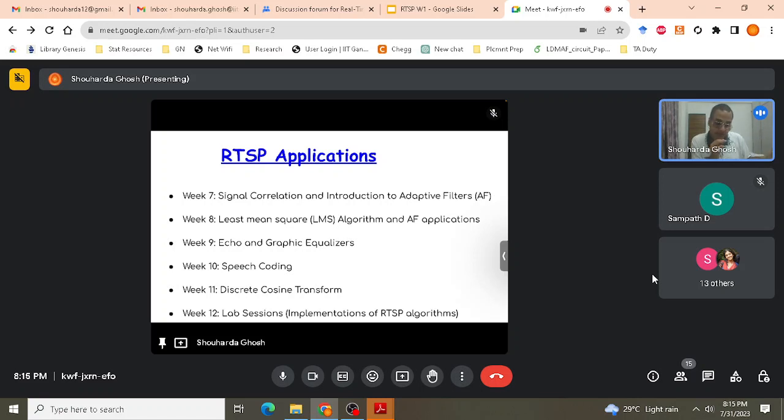Now what actually happens in the experience of the auditorium, how are you able to get that? In reality, the auditorium experience, the reflections, can be modeled by an impulse response. See, I am using a concept of signals and systems to explain what happens in your mobile phone. Your room, our communication, the auditorium's reverberations can all be modeled by an impulse response. And when I say they can be modeled by an impulse response, you can represent it in the form of an FIR filter.